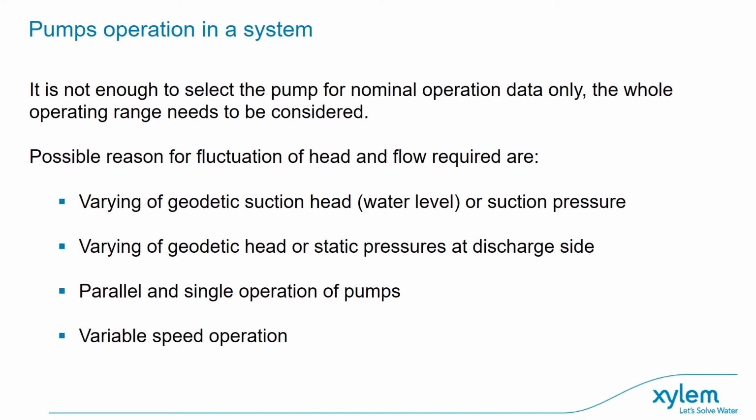And then also, if it is a constant pressure, varying flow demand, then possibly we should be looking at utilizing variable speed operation. Today, many pumps and booster packages generally tend to be variable speed driven as a standard. This gives a great deal more flexibility, means you can have that same constant pressure in a network with a significant fluctuating demand of flow, to actually get the best performance out of the package which you're installing.